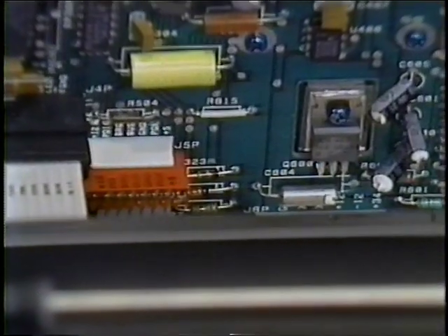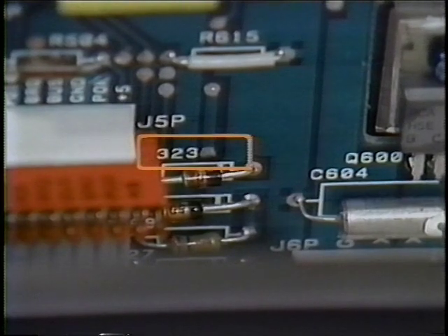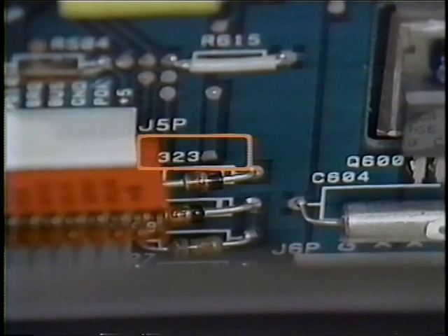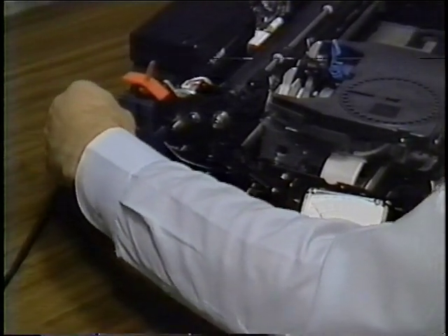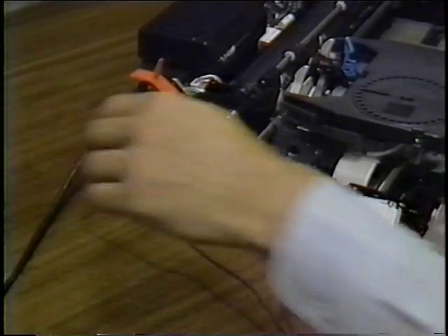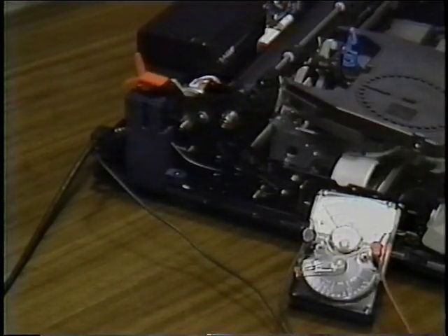This is the sense pad. This pad is used to check for the correct operation of the homing sensor. Let's see how this is done. First, connect the common meter lead to frame ground. Then, turn the machine on